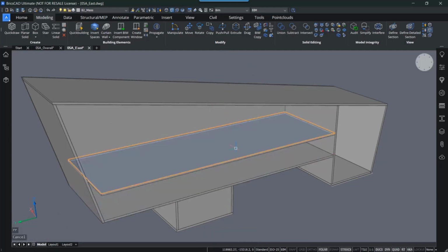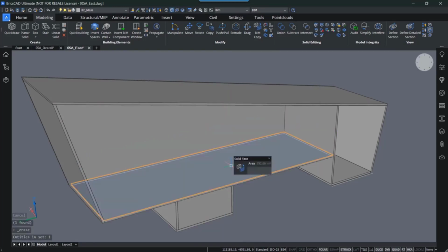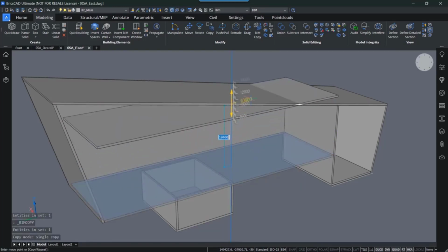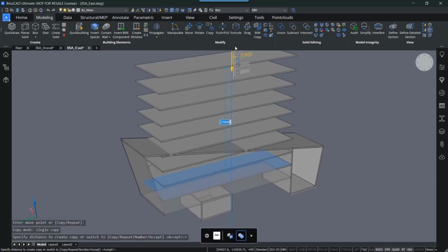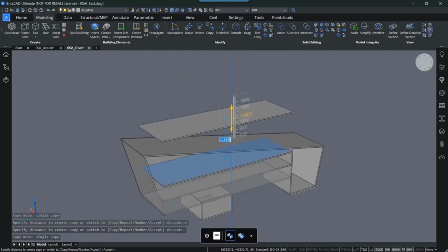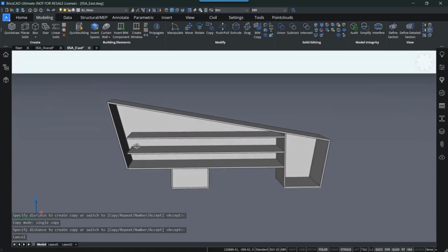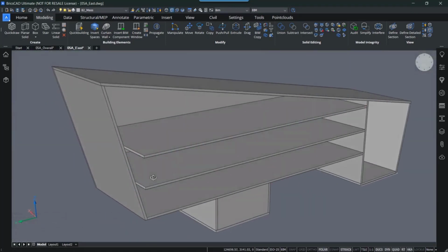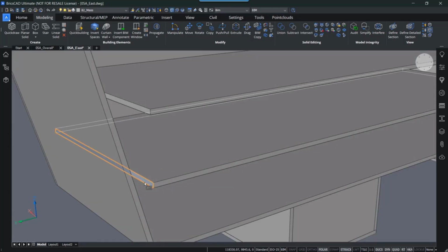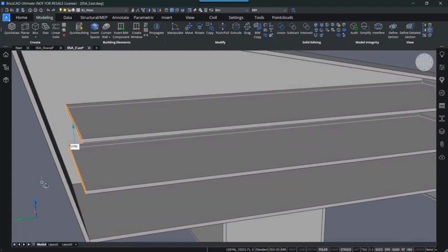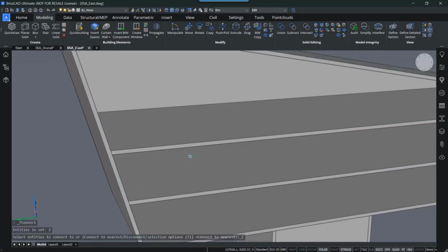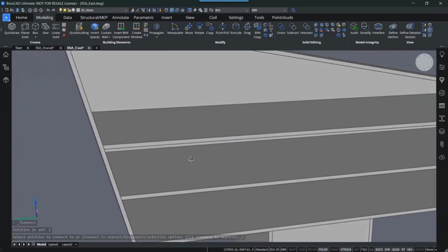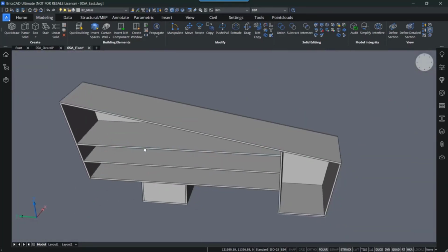Sorry, let me do that again. So just select the solid face, type in 4000, repeat, and then you can repeat it as much as you want, but in this case it's until here somewhere, so just 2 is fine. So like that you can copy around your elements inside your building, and then here at the top I can select both ends of the slab, and then also use connect with nearest to connect it to the wall. So like this, you don't have to manually model it.